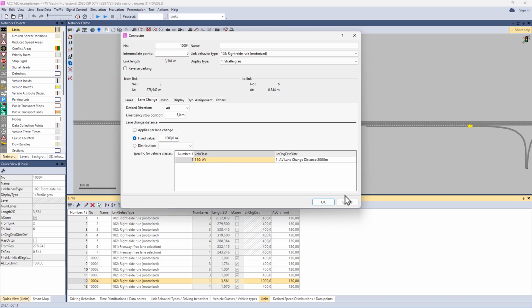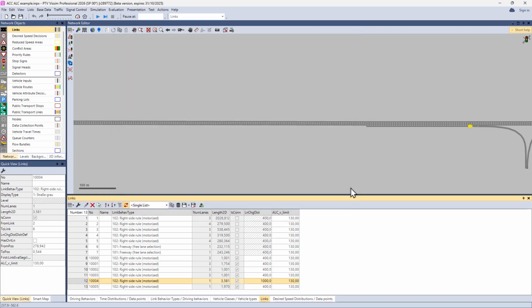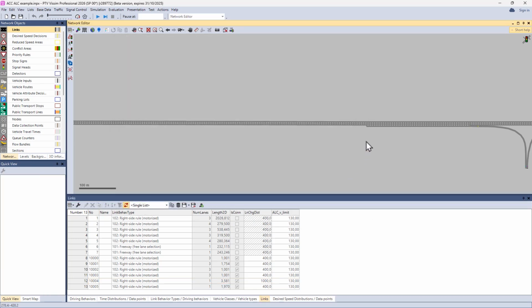And as a rule of thumb, you can go with twice the amount of lane change distance that you would apply for human drivers. Again, a specific distribution, which is actually a constant value, is used to model the impact of this more cautious behavior with respect to necessary lane changes. Okay, that's basically the most important aspects that we have.